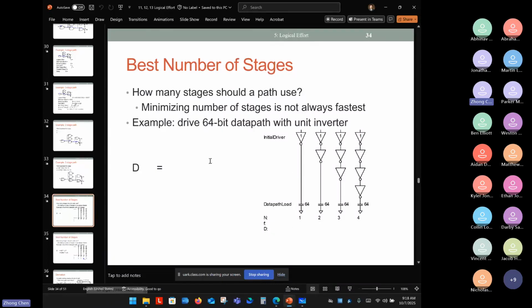So before you learn to optimize anything, to optimize this number of stages, intuitively you might think, all right, a single stage uses fewer transistors and is pretty straightforward. You don't have anything in the middle, which means you don't have any additional input capacitance and parasitic capacitance. It looks like this one may give us the best delay time, because the number of transistors is definitely smaller.